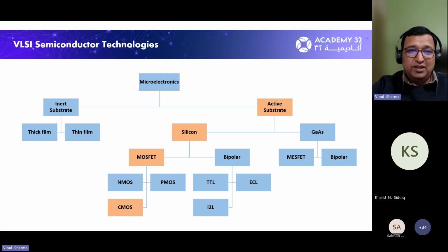More than 90 to 95% of all the manufacturing in integrated circuit technologies happens on a silicon substrate. And even in silicon, transistors can be of different types. For example, there are MOSFETs, bipolar junction transistors (BJTs), and MESFETs. Again, in gallium arsenide there are HEMT kind of devices. Transistors are of different nature based on their architecture, like how the current is controlled through them using gate, drain and substrate structures. But the most used transistor is the MOSFET, and that too on silicon technology.